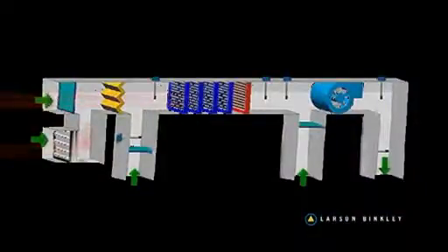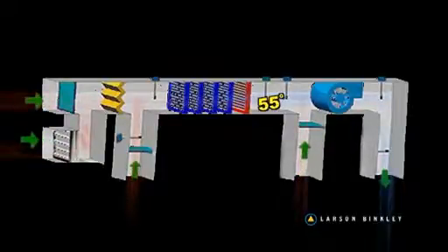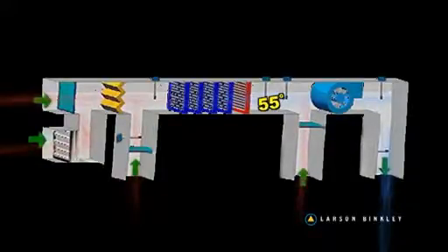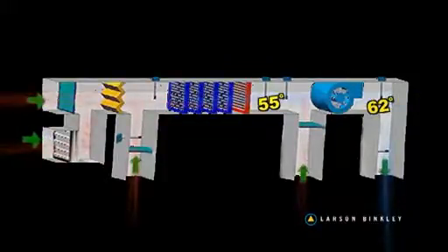Engineers may be wondering, with 60 to 65 degree air, what about humidity? And wouldn't you need twice as much air? We'll save the latter for our discussion about loads, but here's how we handle humidity. Air is brought in through the return of the unit, mixed with outdoor air, and then cooled to around 55 degrees, removing the moisture from the air. The air is then mixed with return air from a bypass damper and then reheated additionally by the fan. We modulate the bypass air based on the relative humidity in the space.